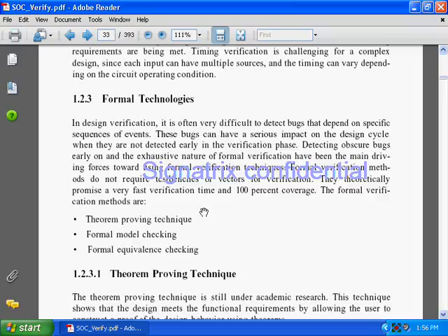Formal verification is simply tool specific. You give your RTL code as an input with some constructs and assertions, and the tool explores each and every corner of your design. But theoretically, a formal verification tool will not work for highly complex designs. For block-level verification, this is a good tool available in the market.